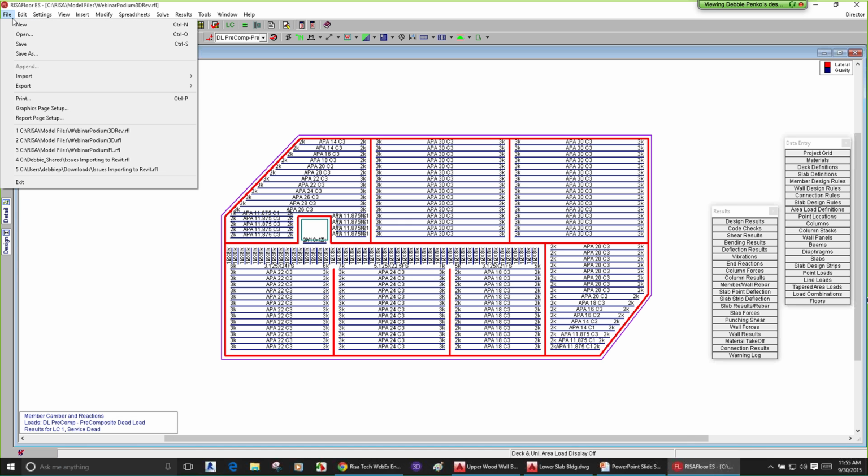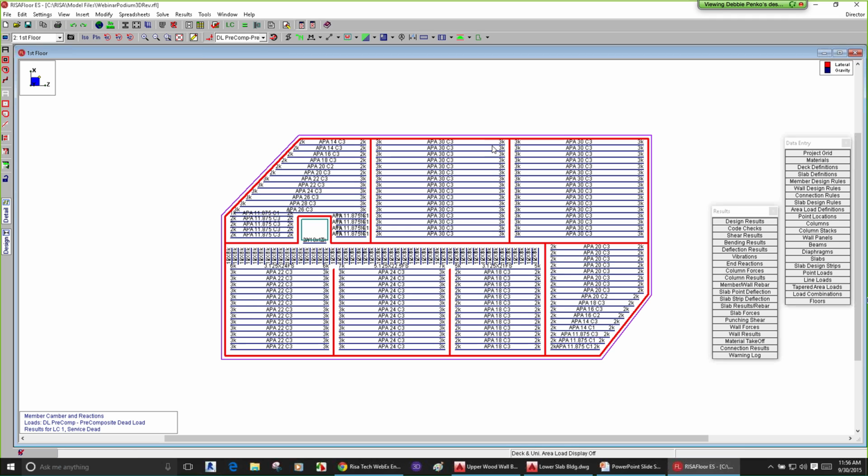The other thing you can do is export over to Autodesk Revit. So instead of using DXF, you can do a Revit model. If you do a Revit model, a lot of the information that's carried across would be intelligent information. So it's not going to just be a label. It will come across with what this actually is as a shape, what the end reactions are. So a lot more information goes across. It's a very smart model when you take it over to Revit Structure.